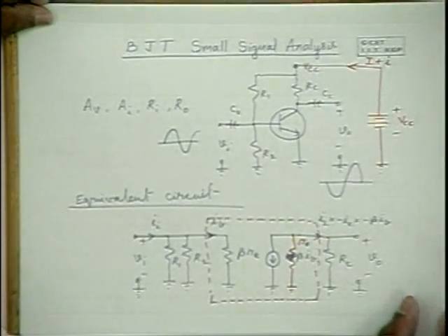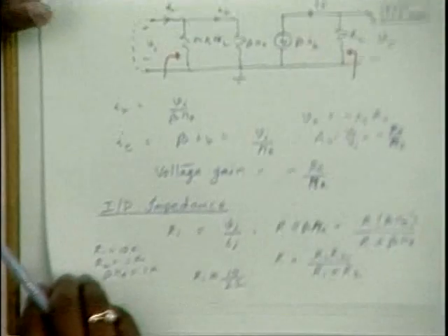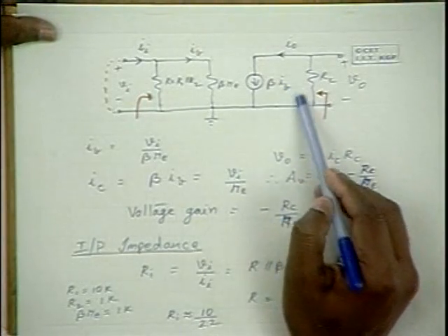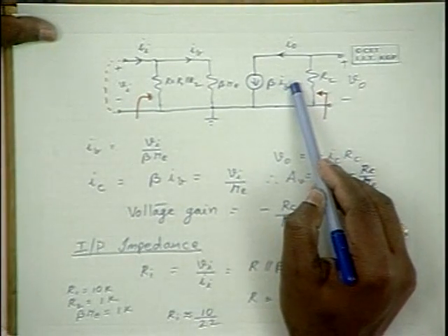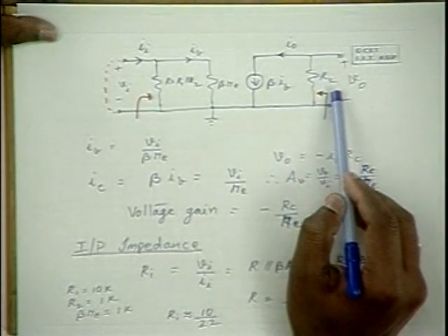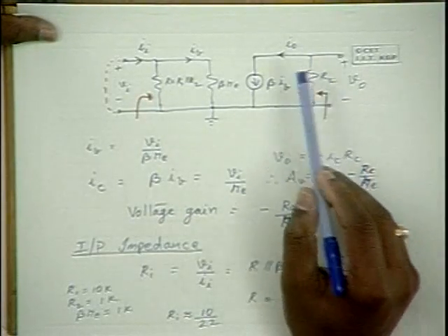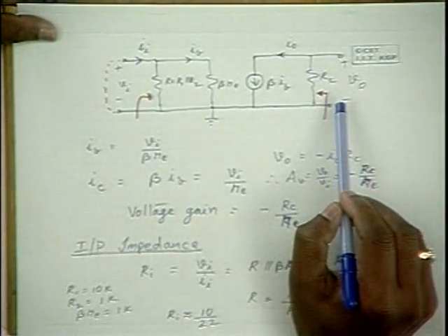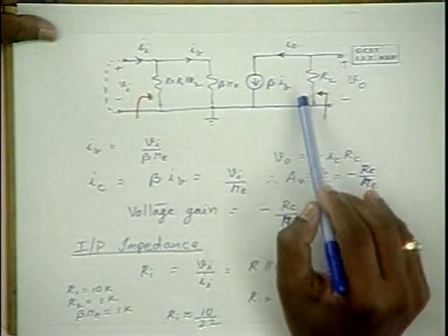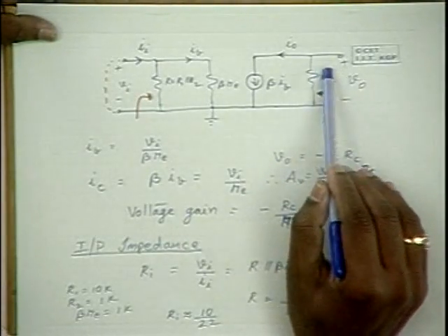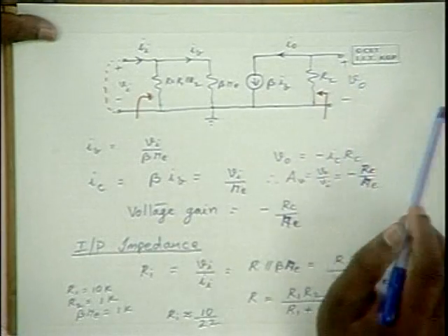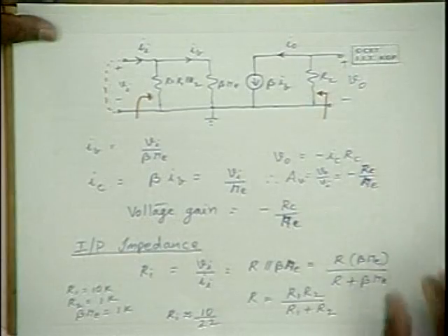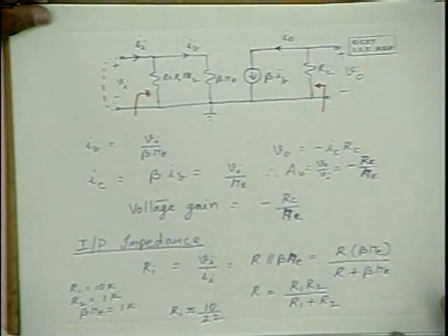And the output impedance over here is approximately infinity. Therefore, when you introduce RC as load resistance, there is no further voltage drop here because of loading. Please note that RC is external to the circuit when you treat RC as the load resistance. Any other question?